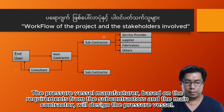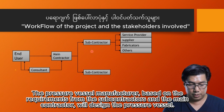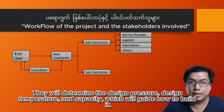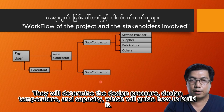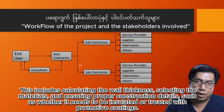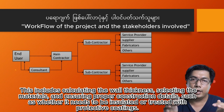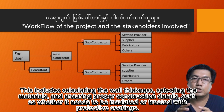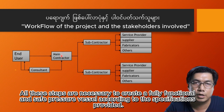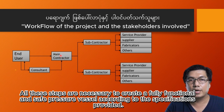The pressure vessel manufacturer, based on the requirements from the subcontractors and the main contractor, will design the pressure vessel. They will determine the design pressure, design temperature, and capacity, which will guide how to build it. This includes calculating the wall thickness, selecting the materials, and ensuring proper construction details, such as whether it needs to be insulated or treated with protective coatings.